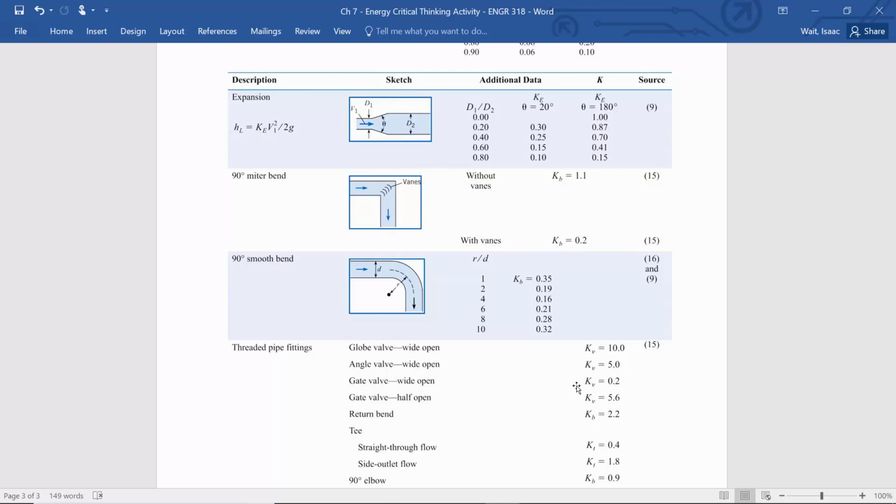It's kind of like a castle door that just goes straight down and can be lifted straight up. So when it's up and it's open, the gate valve doesn't cause much disturbance. When it's closed, of course, it's not letting any flow through there. But when it's open, there's less disturbance than compared to a ball valve that has a small hole through the center.